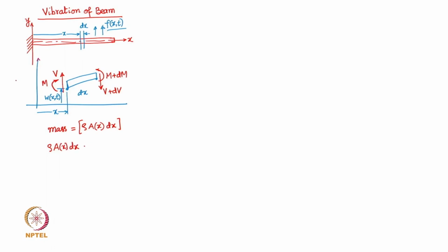So in this case, the lateral deflection and the vibratory displacement is w(x,t) at point x, which we can treat as the reference point, and then write the acceleration of this entire element to be the second partial derivative of w(x,t) with respect to t.